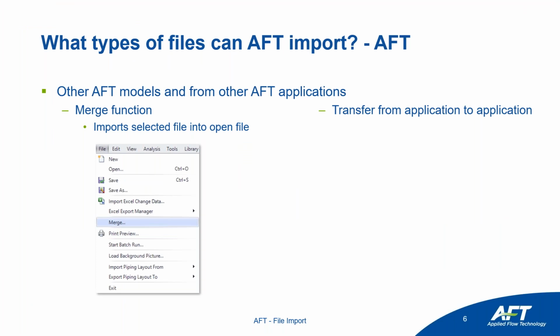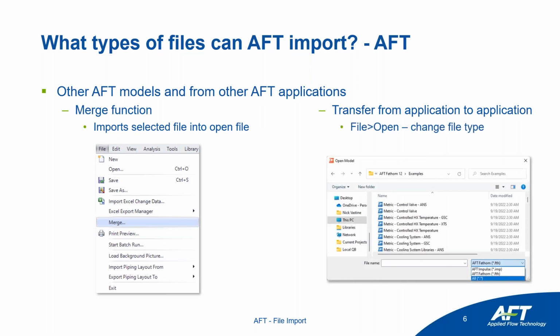So as we saw with the different case studies, we can also transfer files from application to application. In this case, we can transfer it from Fathom, which we would have done all of our steady state analysis. We would have done things like pump sizing or pipe sizing, and now we can bring them into AFT Impulse where we can do our water hammer analysis.